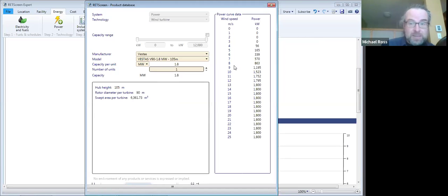So to interpret the power curve, for a value of 8 meters per second, if I had an anemometer and I measured the wind speed at a given point in time, and it said right now your wind speed is 8 meters per second, and then simultaneously I looked at the power output of the turbine, I should be seeing a number around 863 kilowatts. And similarly for the other numbers on here.